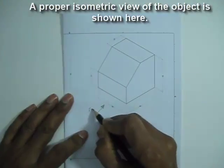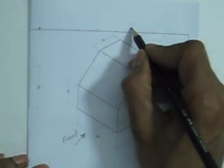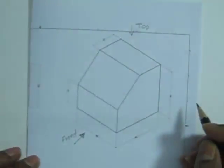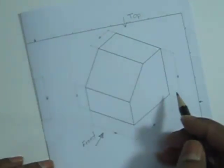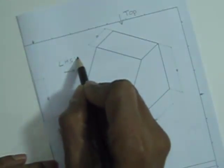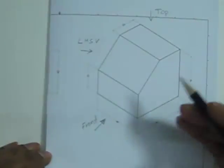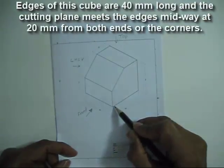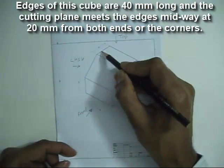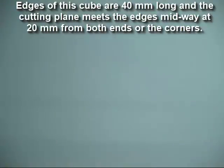So we will take this direction as the front view, and the view from the top will give us the top view. On the left side, we will see the left hand side view. So this is a complete isometric view of the object. Edges of the cube are 40 mm long, and the cutting plane meets the edges midway at 20 mm from both ends or the corners.